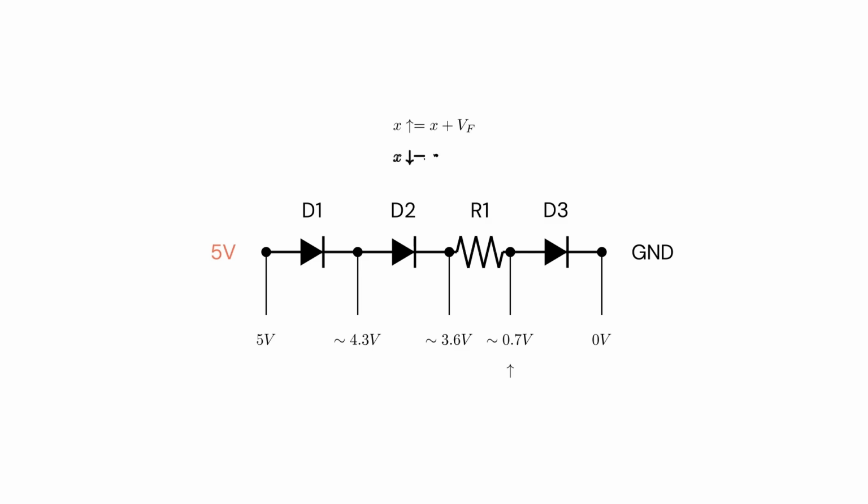A down arrow means subtract one voltage drop. And unless I specify it, I can start subtracting from my top voltage, in this example 5 volts. So the voltage at the cathode of D1 is down arrow, and at the cathode of D2 is 2 down arrows. This seems silly, but it saves some arithmetic, and we don't need exact voltages but just to reason about voltages in a circuit made with lots of diodes. It's enough. This notation will also be helpful later in analyzing circuits with transistors, which rely on p-n junctions as well, and will have similar voltage drops that can be represented with these arrows.